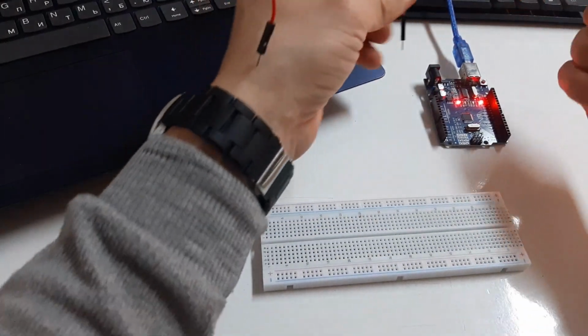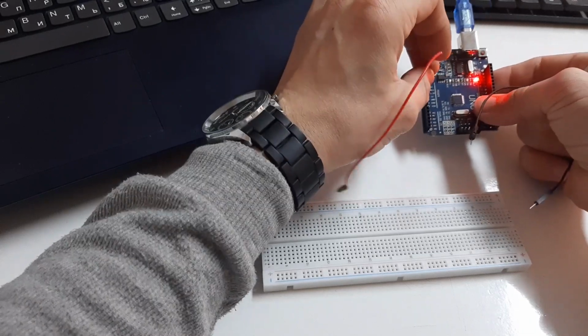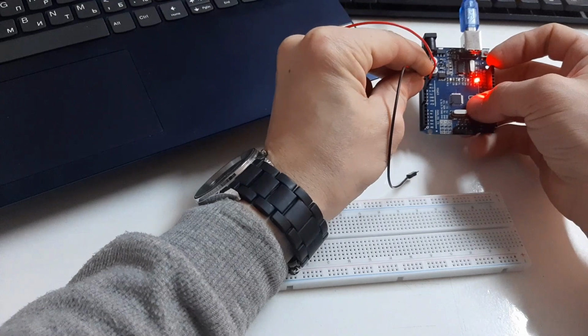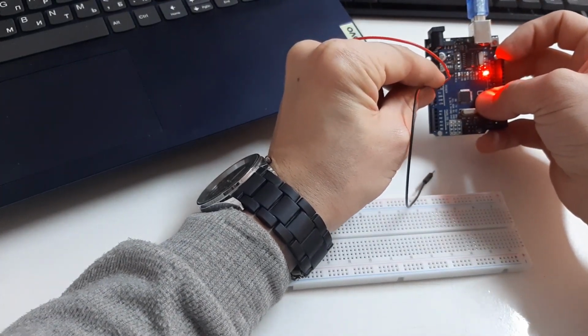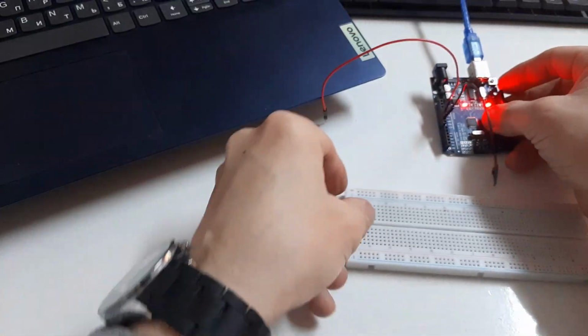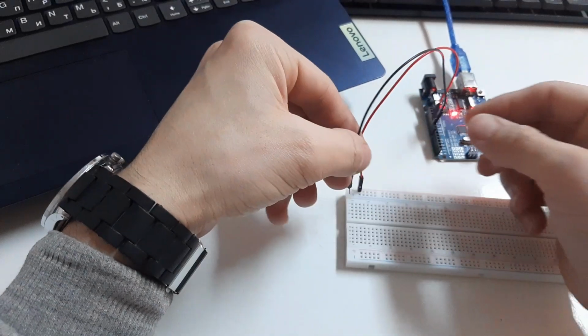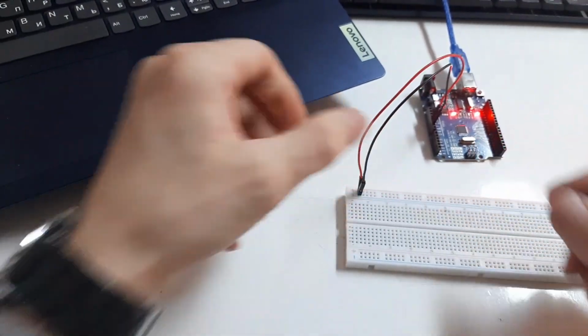Now I connect the 5-volt and GND connection from Arduino to the line with red and green lines on the breadboard with 2 jumper cables, red and black. The colors help us not to confuse the plus and minus lines. Almost all circuits have a red plus line. Now we have 5 volts and a minus line on the breadboard. From here we can build more circuit elements. For now we will use only one LED.